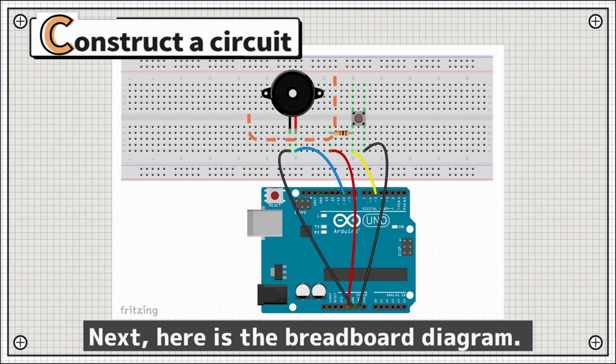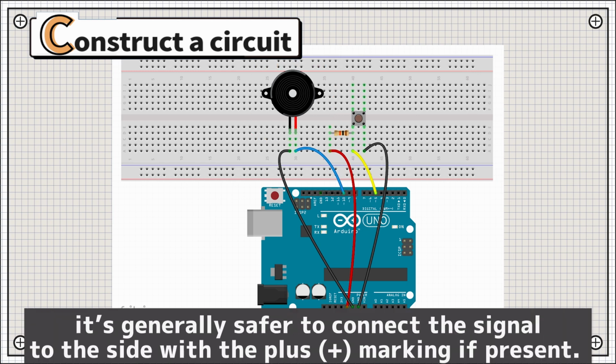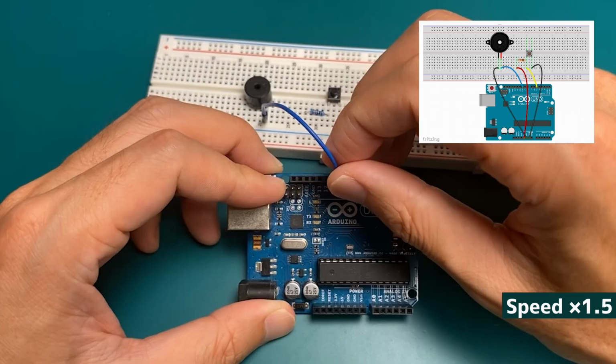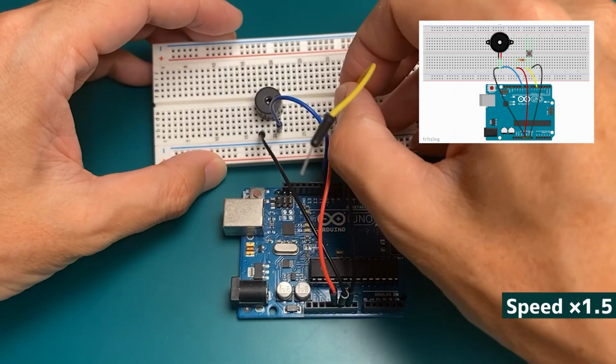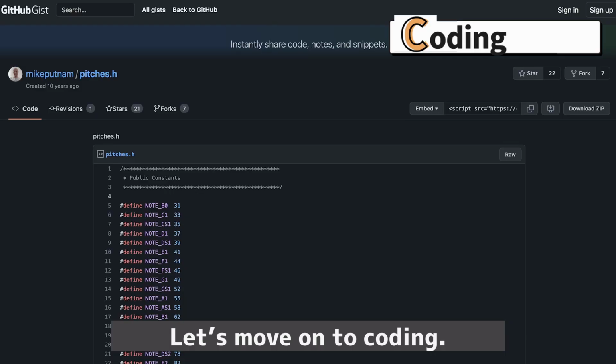Next, here is the breadboard diagram. While the internal structure of a passive buzzer is just a coil, it's generally safer to connect the signal to the side with the plus marking if present. Let's set up the circuit based on the diagram. Now, the circuit is complete. Let's move on to coding.